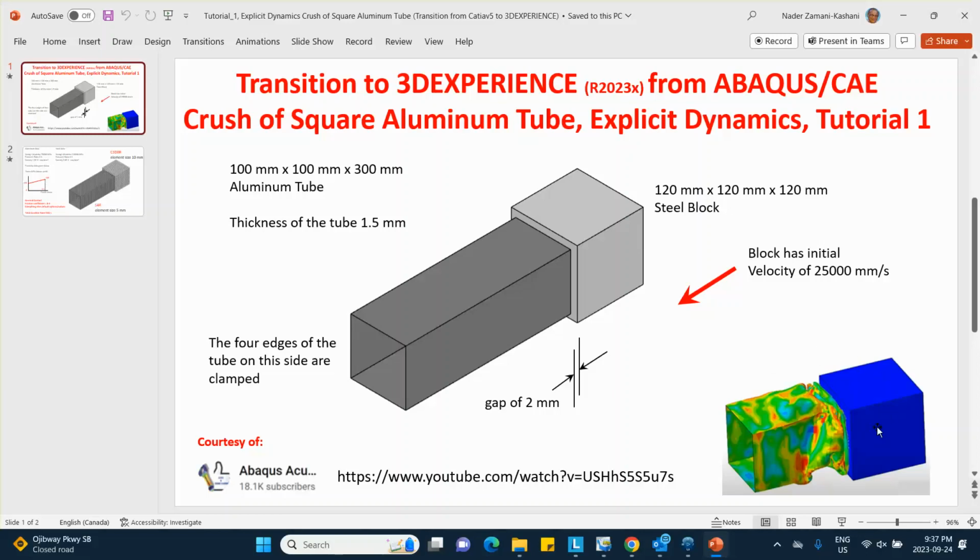We don't even know if these results are accurate because you really have to do some parametric study or mesh convergence study and things like that in order to assess the correctness and validity of the explicit dynamics. Explicit dynamics, basically, you get all the colors that you want. It's just that they may not match reality for different reasons.